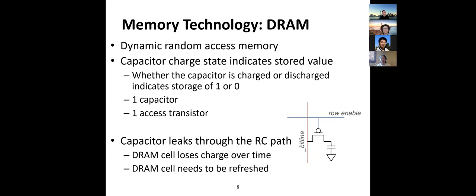So the key thing, without going deeper into DRAM organization, the very important part for you to understand, and that's a big weakness of DRAM, is that the capacitor leaks charge over time. So if I leave my memory without recharging it, with the power on all the time, it's going to lose the charge. There are all these famous movies about people trying to steal information from someone. And there were rumors that if you grab DRAM and freeze it in a special way quickly, you might actually retain the information. And it's not completely impossible.